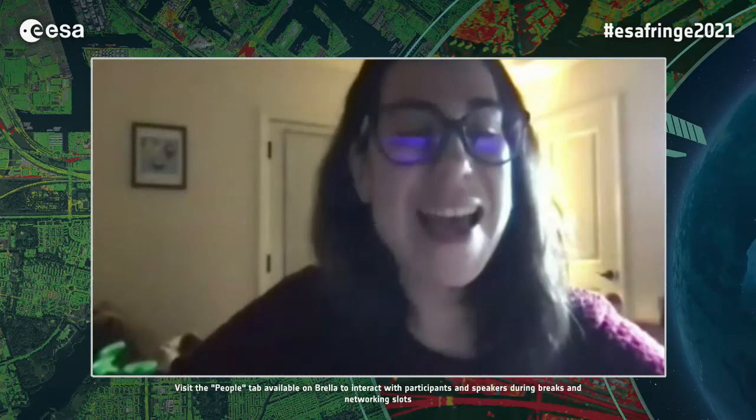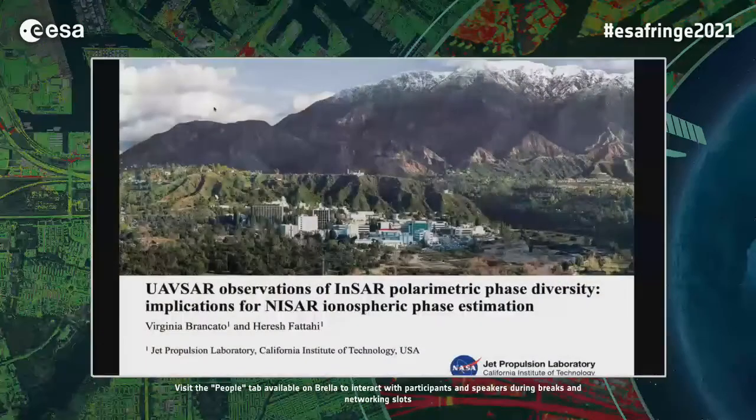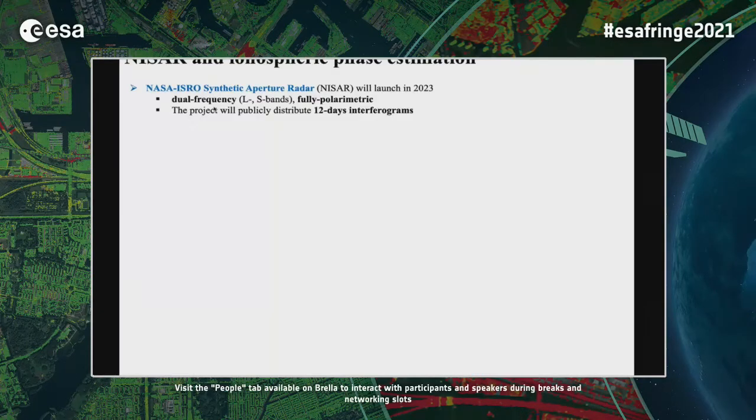So welcome to the first presentation of this session. This talk will briefly summarize the work that my co-author Eresh Fattahi and I have been doing regarding the estimation of the ionospheric phase screen for NISAR L-band repeat pass data. NISAR is a dual frequency repeat pass SAR mission with fully polarimetric capability. The project will process and publicly distribute interferograms with a 12 days temporal baseline.